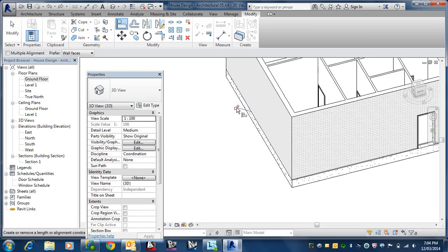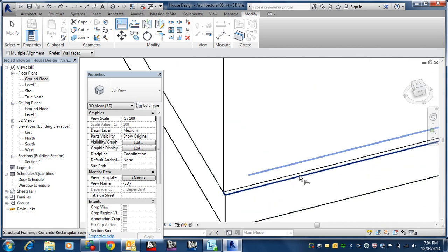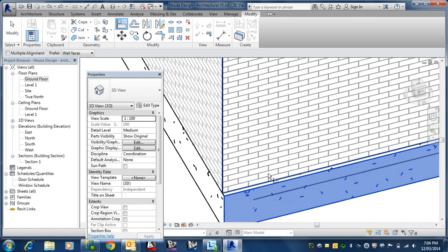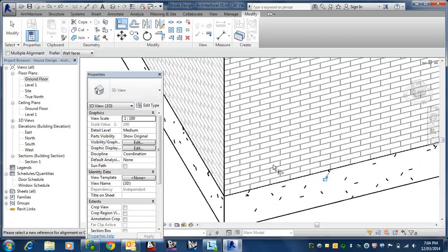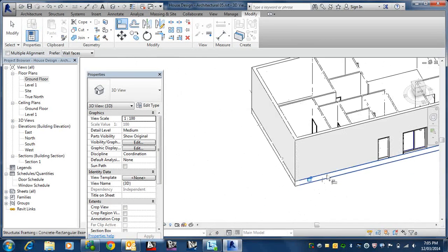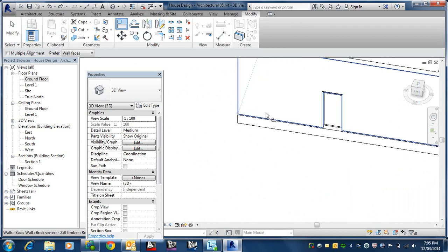All right. Also, sometimes it may already be aligned. It might have come out right, but you go through and do the align command anyway, because then it gives you the opportunity to get the lock and lock it, even though it might be working out okay to start with. So I'm not doing it in this instance, but you can lock it if you want. Good practice to lock it.